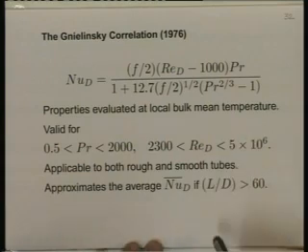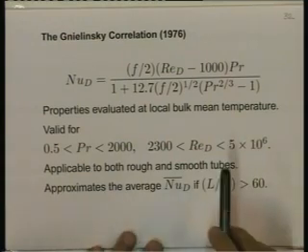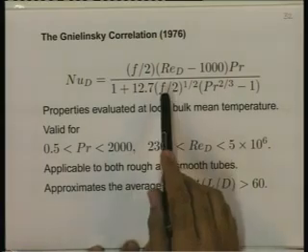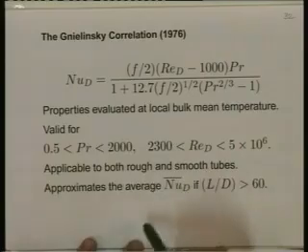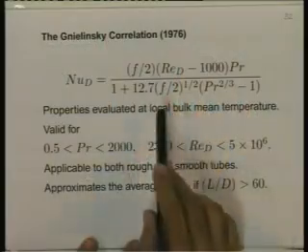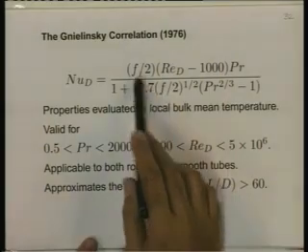This also is a higher range. Depending on the smoothness or the roughness of the pipe, this can be applied by using appropriate correlation for F. For a smooth pipe, you use a correlation for F which pertains to smooth pipe. For rough pipe, the effect of epsilon by D or E by D can be included using the Chen's correlation. So, the effect of smoothness or roughness of the pipe is included through the effect on F.